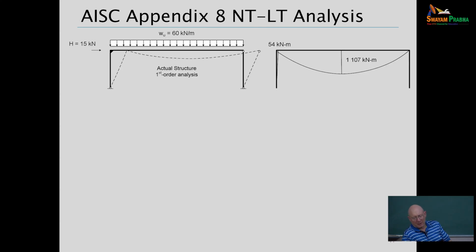So for starters, let's say we did a structural analysis on the frame I just showed you. In that case, this frame would have lateral deflections like you see shown in the dash lines, and moments. Clearly the dominant moment is actually in the roof girder, but those small moments in the left-hand lateral load resisting column are of course very important.